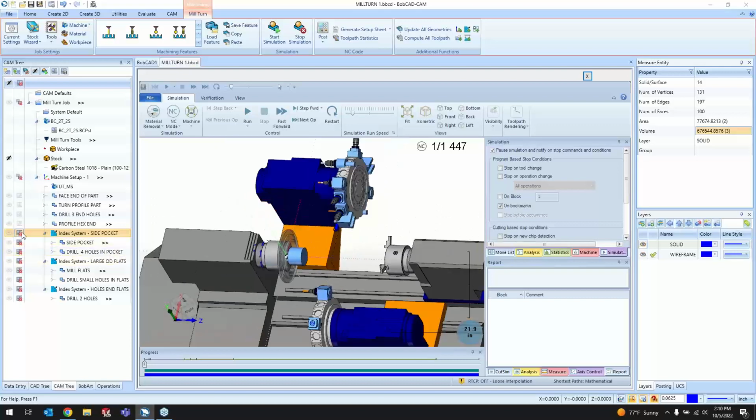And it will also, so if I have only these 4 turned on, it will only post the G code for these 4 features and won't post the rest of what I've got programmed. If I don't want to post the G code for the profile hex, for example, I just turn that off, and when I post, it won't post that feature as well.